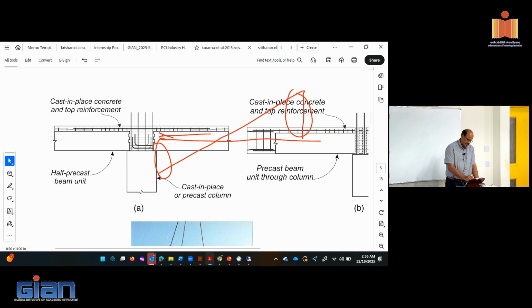So the same thing as what I explained to you last time would happen, like what we discussed about what happens in the plastic hinge region. So it's important to realize that when you detail this region, you don't put in any additional reinforcement. You don't unnecessarily strengthen that region by putting couplers or lap splices and things like that.